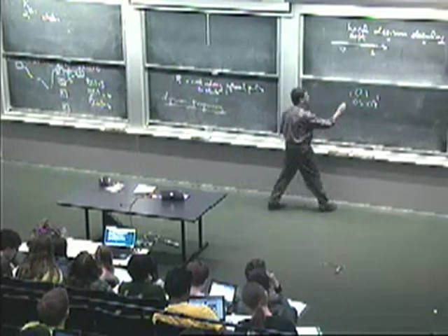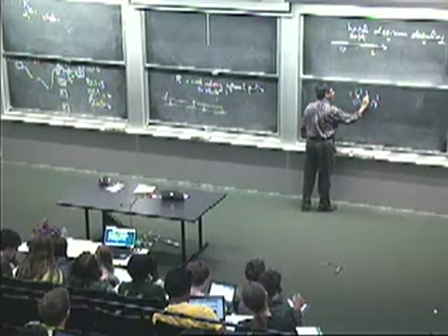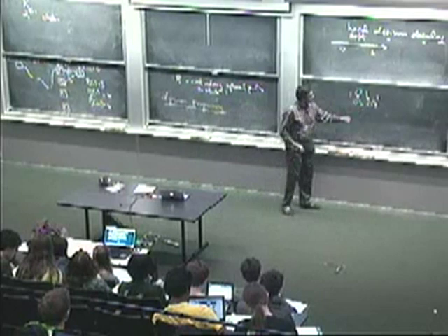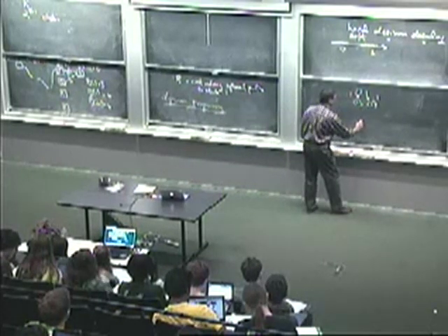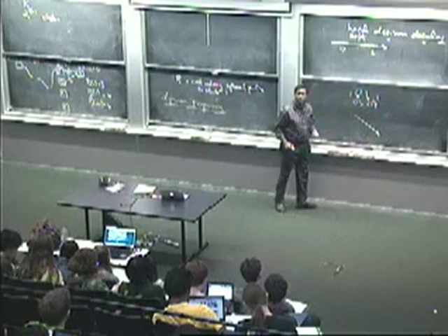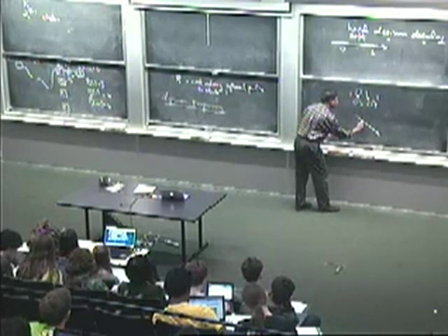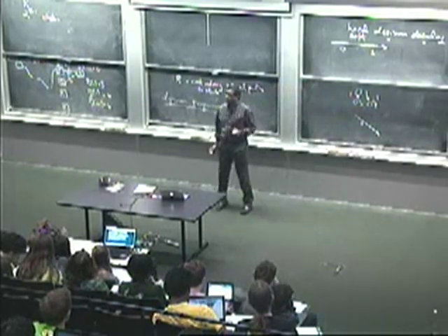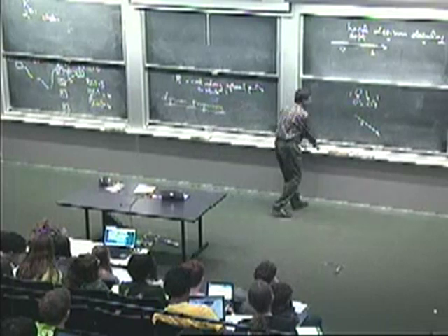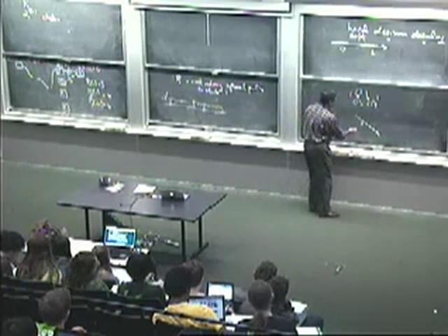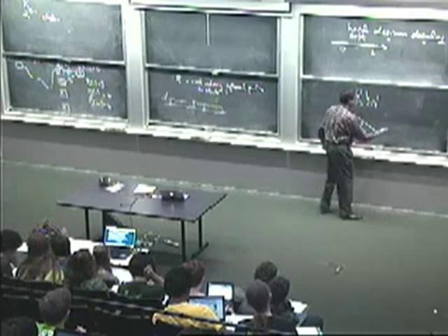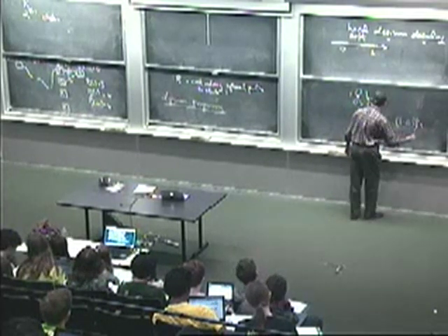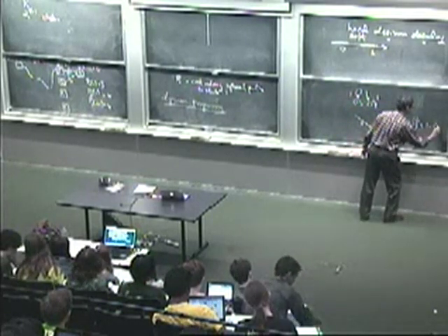And you had actually translated them to a 0 and a 1 in your hard decision decoding. All right. If you decide not to do that, but to stick with these numbers, then what you have is the task for any particular edge that you're traveling on of finding the distance between the parity bits you would emit on that edge and the samples that you have here. It turns out that a very widely used cost for soft decision decoding is the sum of squared differences. So what you would have is 1 minus 0.3 squared plus 1 minus 0.7 squared.